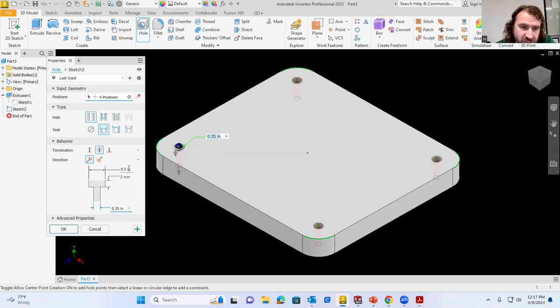Okay, so if I go to counter bore, there are different counter bore dimensions you need to know about. This one here is the counter bore diameter, which is the diameter of the larger opening circle. So this larger opening circle, let's set this at 25 millimeters. We'll just make sure that it's mm and we should be good, right? So that sets it at that. We can see that previewing there.